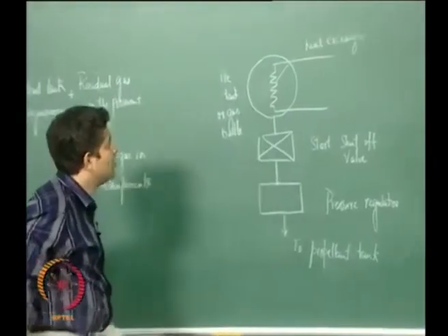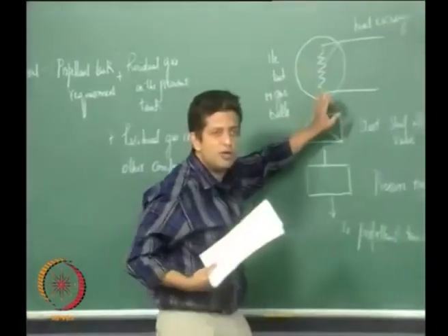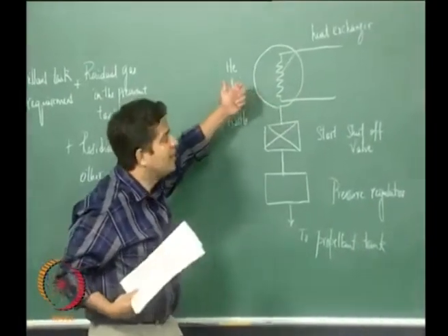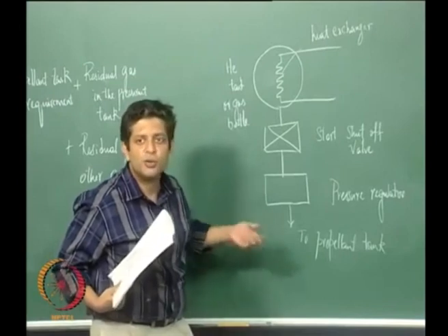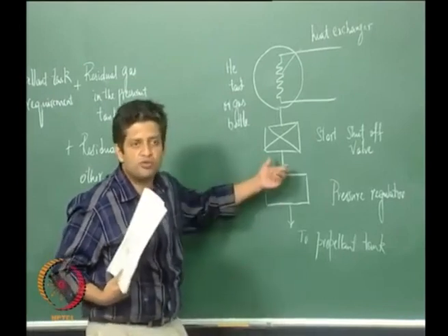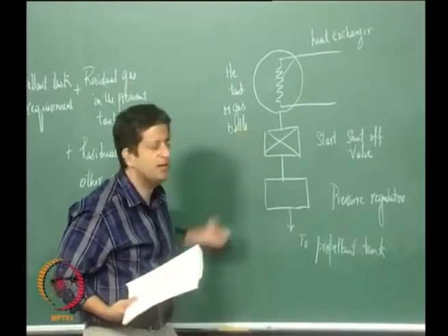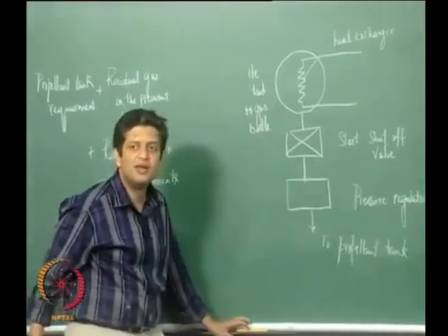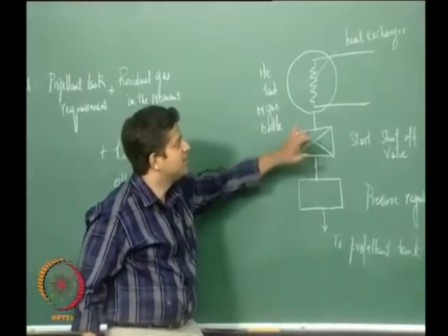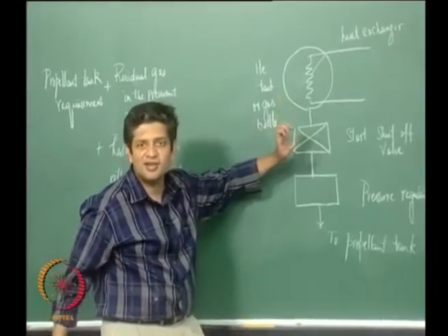Okay. If you have a heat exchanger here, as the helium cools down, if you supply heat to it, then the temperature won't drop so much, and therefore you will have a lot more useful pressure. Okay, this is one way of doing it, but the trouble with this kind of a design is, you are designing a gas bottle which can withstand very, very high pressures, right.